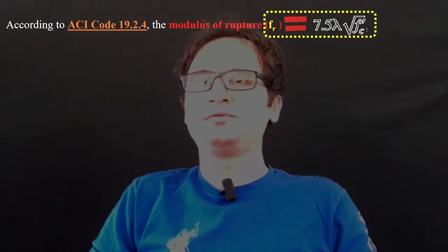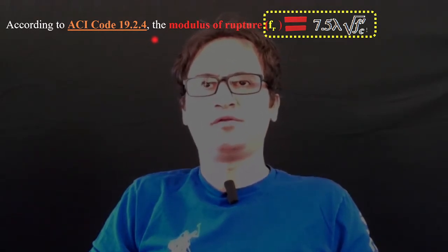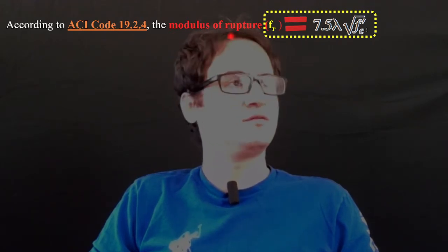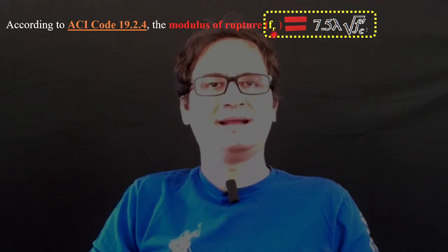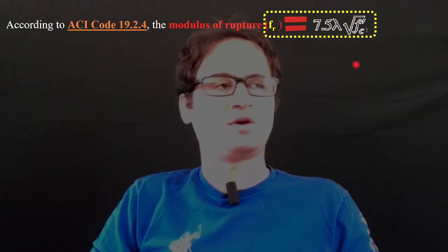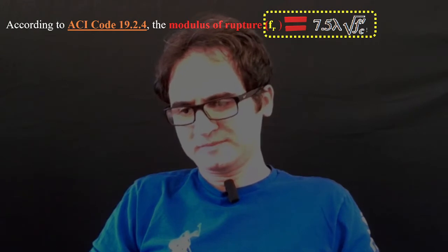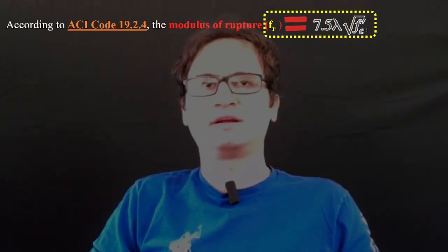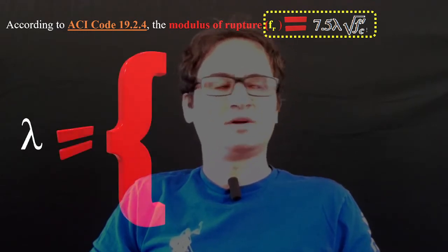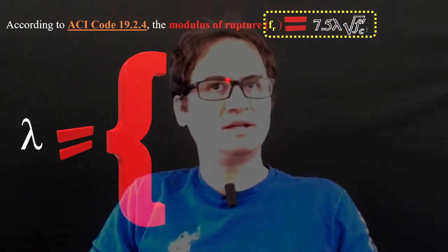So according to ACI code 19.2.4, the formula for modulus of rupture for concrete is Fr, and that's equal to 7.5 times lambda times the square root of F prime C, concrete specific strength F prime C. So let's see what's lambda in this equation for modulus of rupture, which we'll talk about later on.